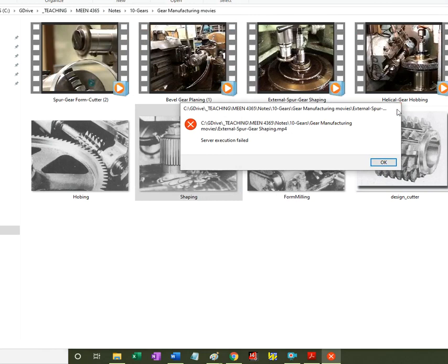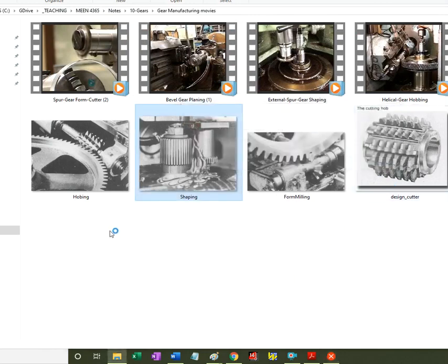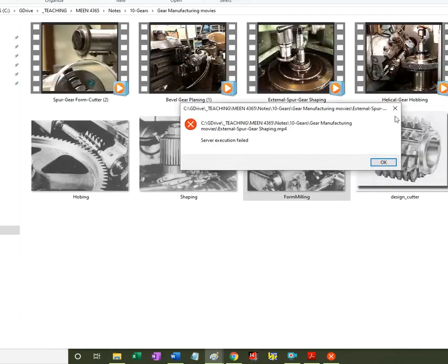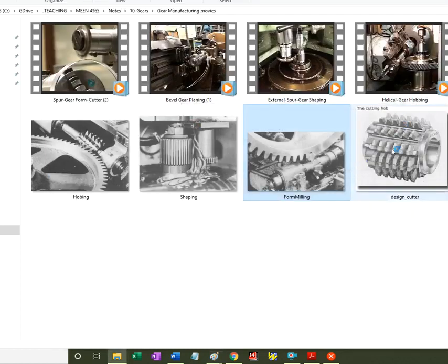And then the most productive process, again, this is for milling. You just have an end mill that removes the material and it forms the tooth. The problem is that you would need a different formula for a different number of teeth because their geometry changes. So you can use the same tool for, say, plus minus 1 tooth. So if this is made for 35 teeth, you can use it for 34 and 36, allowing for some imperfection.